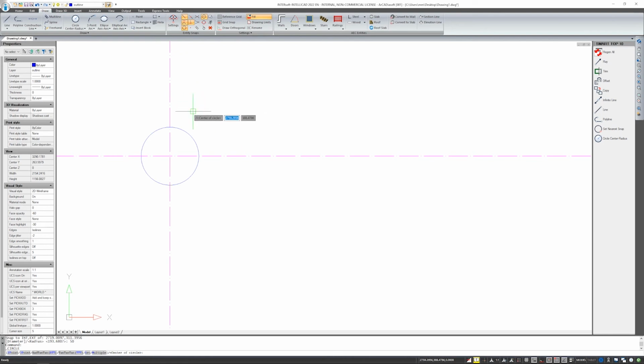And it is very difficult to target the one that you would like, the center of the circle that is already inserted. Very often you turn on all possible snaps, and then there is such a situation that the appropriate one does not turn on. Therefore, it would be best to disable these snap points and only use the most frequently used ones. I suggest that the nearest snap be turned off. The nearest snap point, that is the one that shows around the entire circle along the length of the line, is not a very precise snap point.